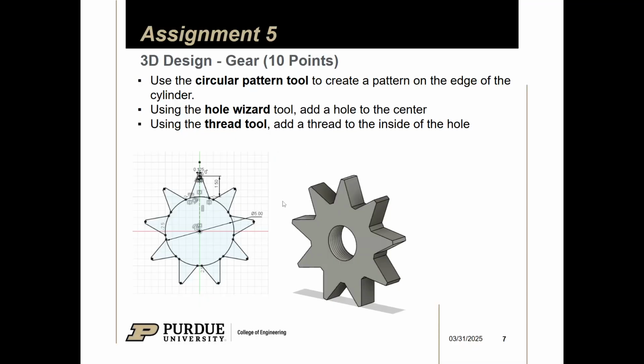So what I'm going to do is create this circle, and then I'm going to create a singular tooth, right? Again, the cool thing about CAD is that you can use the computer to do a lot of stuff for you. Because something like a gear or maybe a pulley has teeth that are all symmetrical, or the same for the whole profile, you can model one of them and then copy it multiple times throughout your design, right?